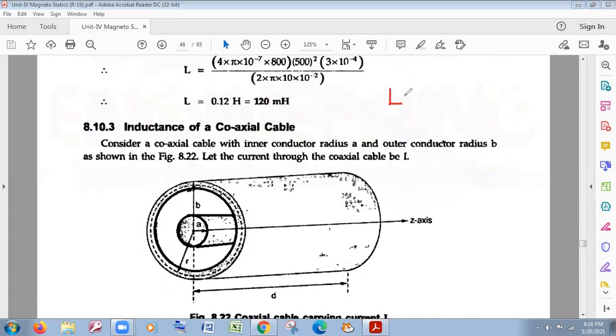To find the inductance, L is equal to total flux N phi by I, that is N into phi by I, where phi is equal to the integral of B bar dot dS bar, as in the vector product, or B into the integral of dS. The integral of dS is a differential surface, meaning it has the area only, so B into A by I.